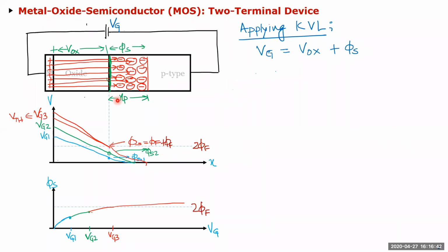Okay. So the question now is, so this is called the threshold voltage. It's the voltage of this metal with respect to the substrate at which this material here at the interface turns into N-type. And that's called your inversion channel, and that's your threshold voltage, right? So now I want to find out what that value is. Like, what is that voltage value? Is it minus 0.1, 0.2, 0.3, 0.4, 0.5? What is it? So that's what we're going to do next. So what is that value?